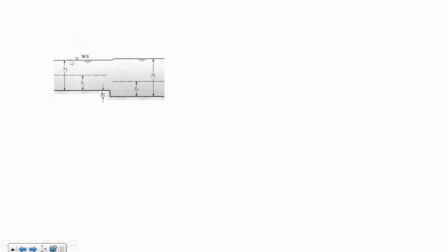So what's the flow regime at location 1? Subcritical. Right. I'm going to keep asking that to reinforce your ability to see if conditions are sub, super, or critical. So here, at location 1, conditions are subcritical. That's another clue that we get from the sketch here.